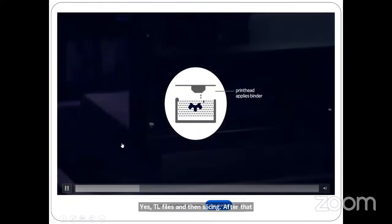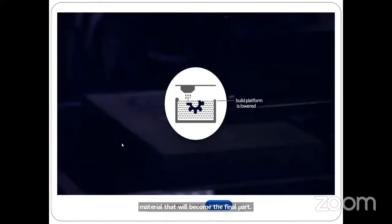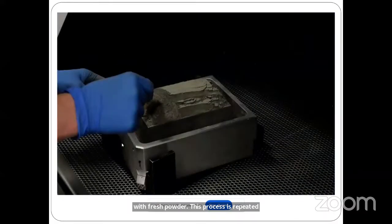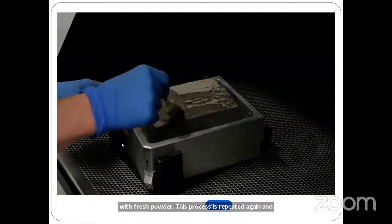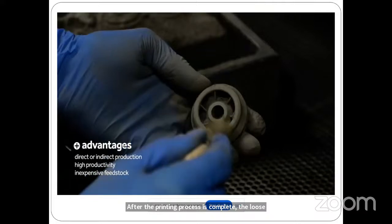The print head then applies the binder to the areas of the powdered material that will become the final part. The build platform is lowered, and the entire surface is recoated with fresh powder. This process is repeated again and again to build up parts layer by layer. After the printing process is complete, the loose powder is removed, and a 3D printed part is extracted.